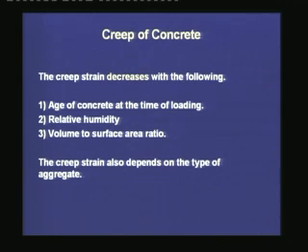There are several factors for which the creep strain decreases. The first one is the age of concrete at the time of loading. If we delay the loading of the concrete member, whether it is the prestressing force or the service loads, then it is found that the creep strain is reduced. Second is the relative humidity. If the relative humidity goes up, the hydration gets better and the creep strain reduces.